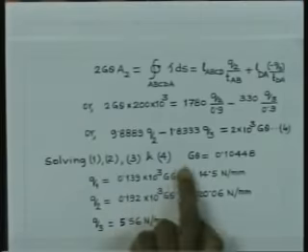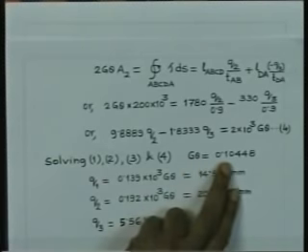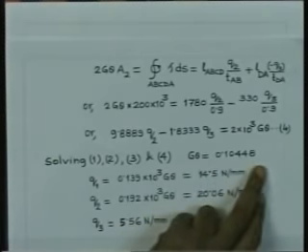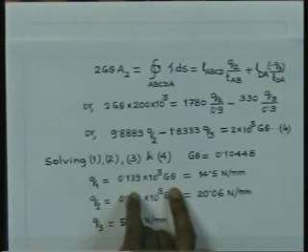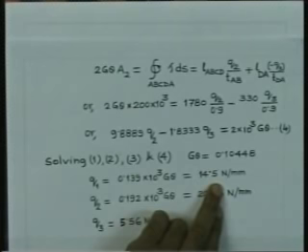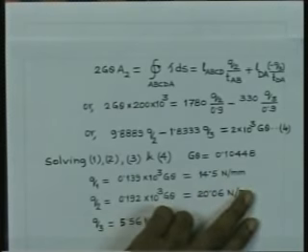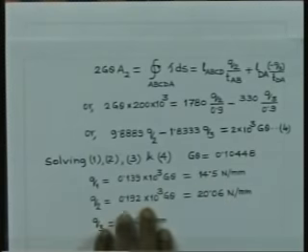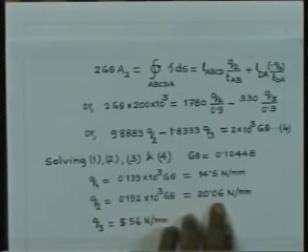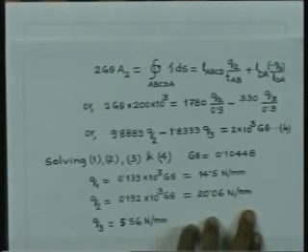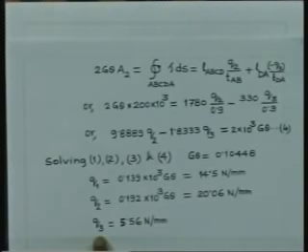Once you solve it, you obtain g theta as 0.10448 and Q1 equal to this, which is equivalent to 14.5 Newton per millimeter. Q2 is 0.192 into 10 to the power 3 g theta, which is nothing but 20.06 Newton per millimeter, and also you can obtain Q3, which is 5.56 Newton per millimeter.